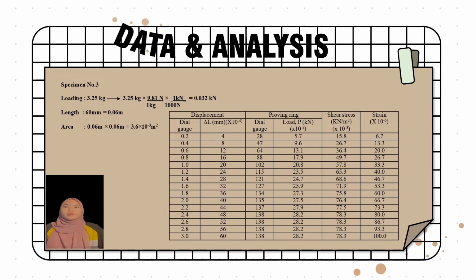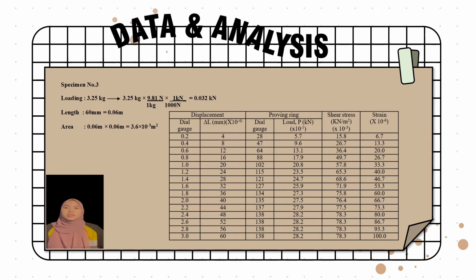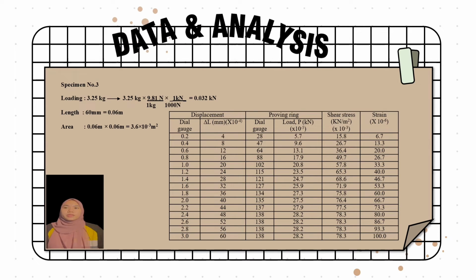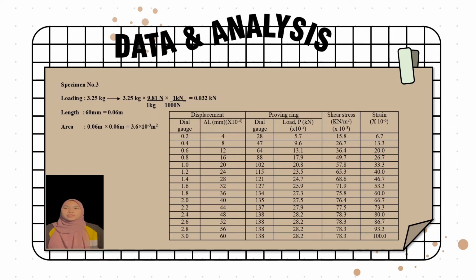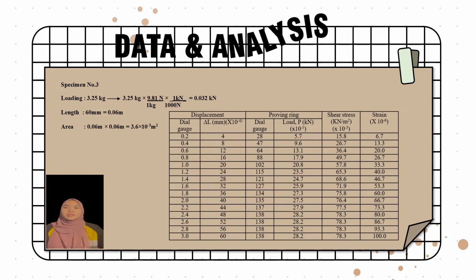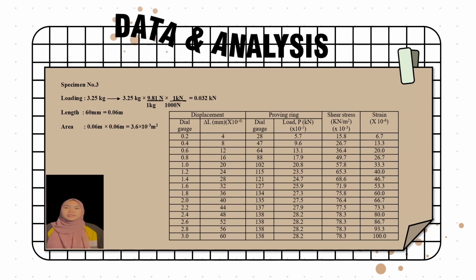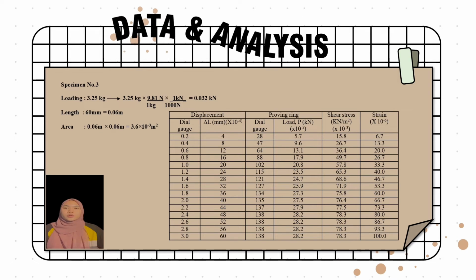Other than that, the volume change in sandy soil is a complex phenomenon depending on gradation, particle shape, state and type of packing, orientation of principal planes, principal stress ratio, stress history, magnitude of intermediate principal stress, type of apparatus, test procedure, method of preparing specimen and others. In general, loose sands expand and dense sands contract in volume on shearing.